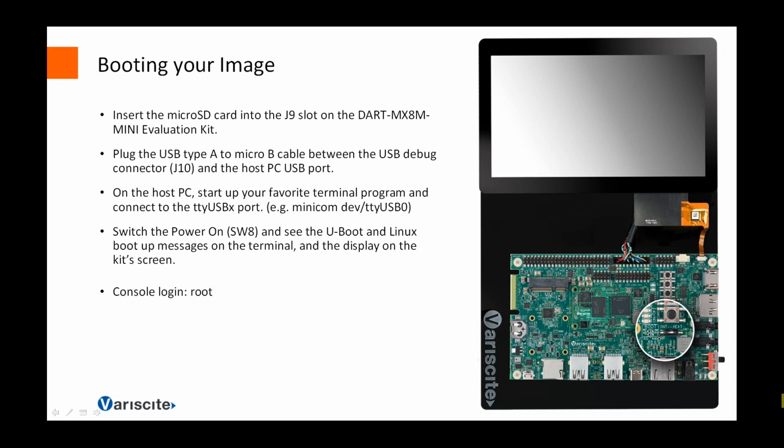Once you have the recovery SD card ready and you have installed it on the eMMC, you can start testing at least the hardware. We have a dedicated section in our wiki for the how-tos where you can check how to test the audio, how to test the UART, how to test the I2C, something that does not really require you to build something custom. It's just something standard.